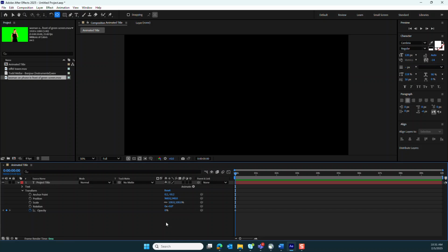So now we're going to go 12 frames out. And the way we're going to do that is you're going to use your page up or page down. Page down will move you to the right through the timeline. So we're going to press that 12 times. So if you press page down on your laptop, 1, 2, 3, 4, 5, 6, 7, 8, 9, 10, 11, 12. That's halfway through our frame rate. We have 24 frames per second. So we're doing half a second at 12 frames.